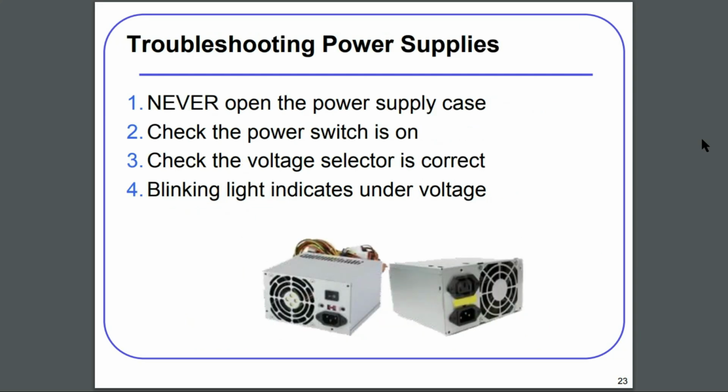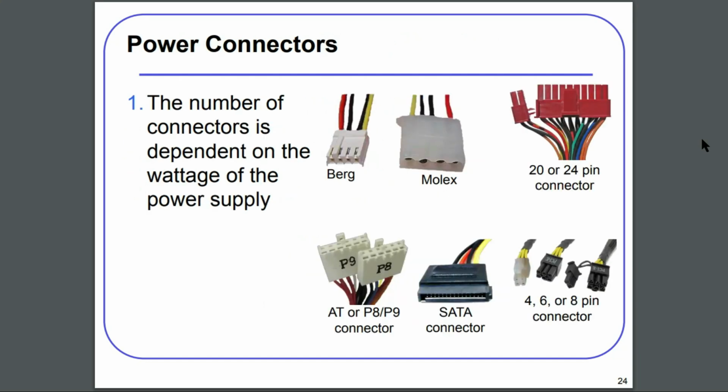So in this slide we can check how to troubleshoot the power supplies. Never open the power supply case, check the power switch is on, check the voltage selector is correct, and a blinking light indicates under voltage. So let's move to the next slide.